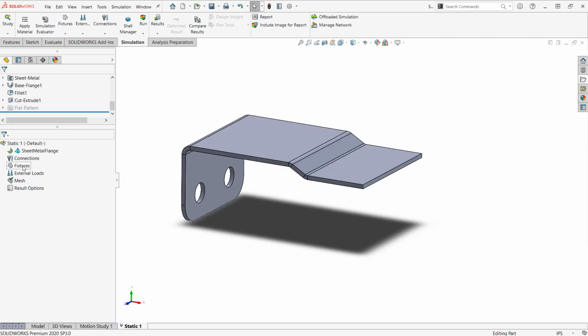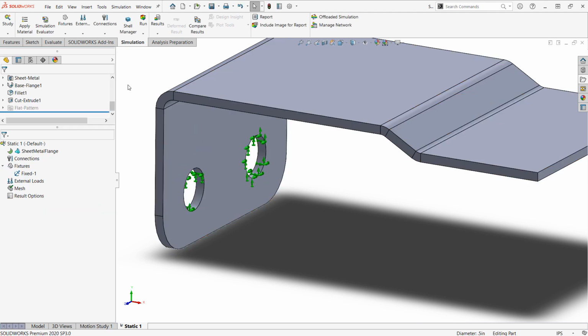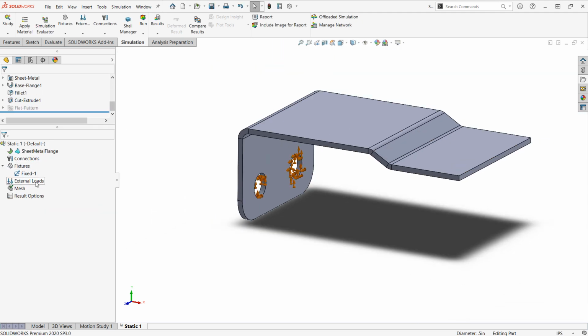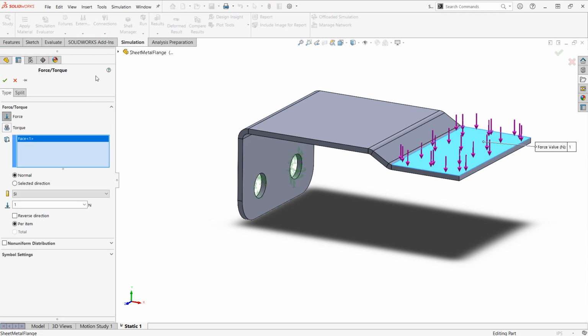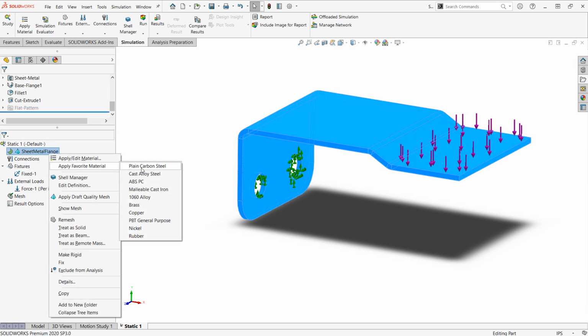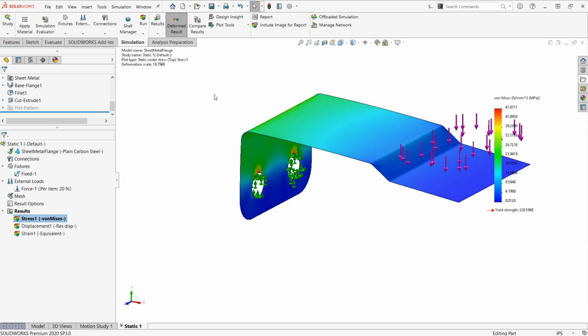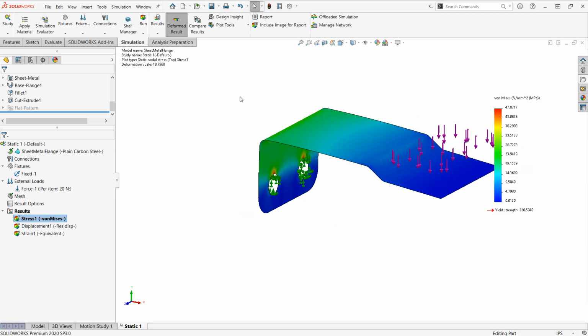But then there's other benefits to the sheet metal conversion, such as it doesn't care which selections we make. I can choose cylindrical faces, I can choose particular edges, and it won't give me those errors about selecting an entity on the shell. So we can very quickly set up a sheet metal model using these types of definitions and still take advantage of our shell.